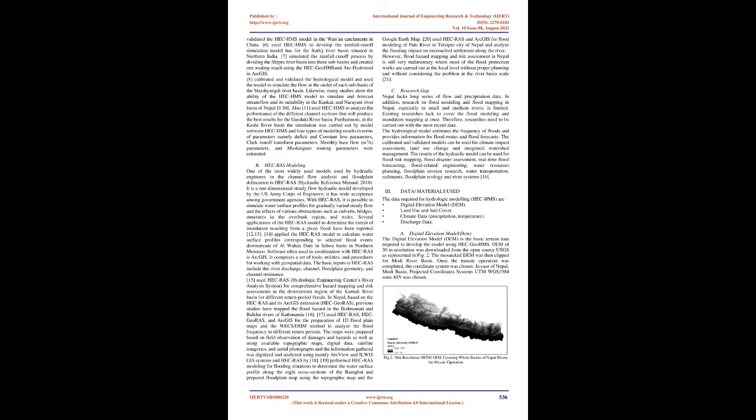HEC-HMS uses separate models to represent each component of the runoff process, including models that compute runoff volume, models of direct runoff, and models of base flow. Each model run combines a basin model, meteorological model, and control specifications with run options to obtain results. The selection of an appropriate model for each component depends upon the applicability and limitations of each method, availability of data, suitability for the same hydrologic condition.